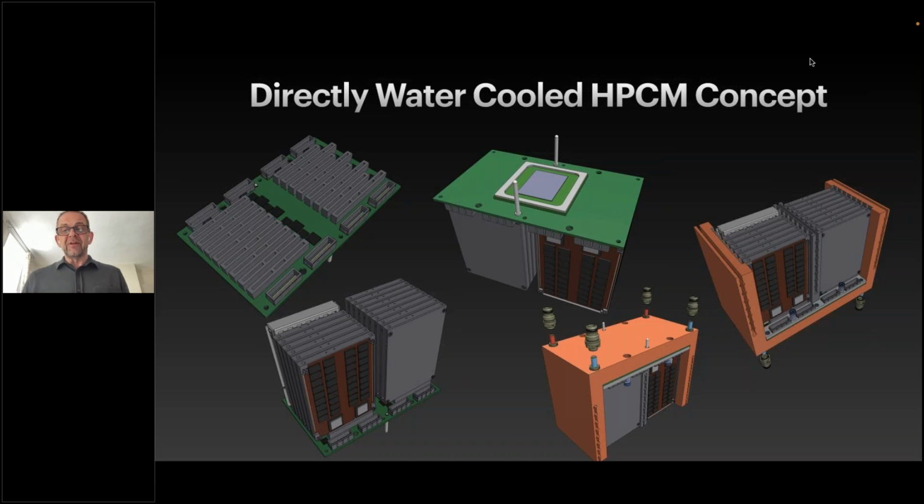So we're using the module like a backplane that can be populated with media, and on the front side, we have this very powerful processor, and/or accelerator, and/or switch, etc. The 4 connectors around those are basically standard MCIO connectors in this particular incarnation, which supports PCIe and will support CXL as that comes in, because that's over PCIe. But the idea of this module is protocol agnostic; this is the fundamental mechanical and electrical interconnection.